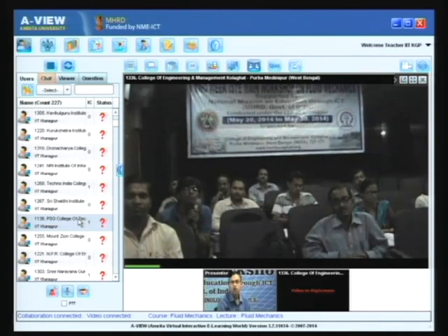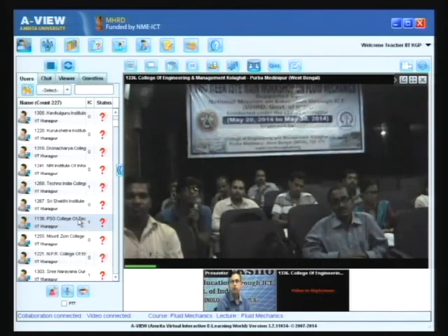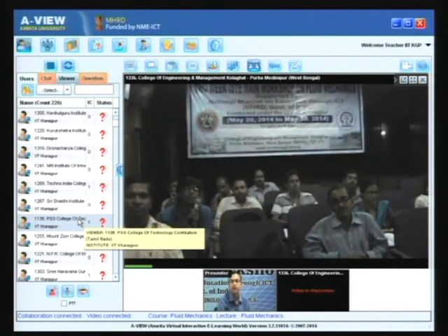If you consider the 4 facet material element, 3 of the 4 faces have normals along x1, x2 or x3, and the 4th face has a normal along an arbitrary direction. If you make a force balance on that element, it is possible to express the force on that arbitrary plane in terms of forces on the 3 other planes, which are perpendicular along x1, x2 or x3. That is why that 4 facet element is chosen.